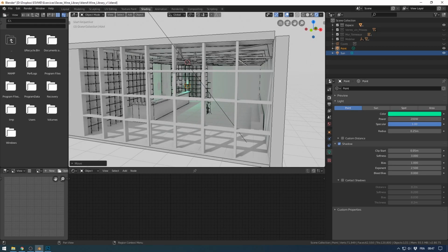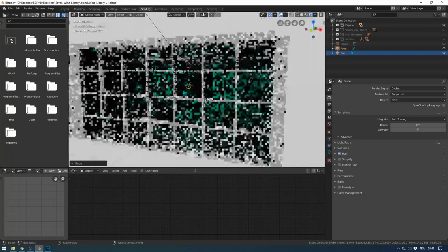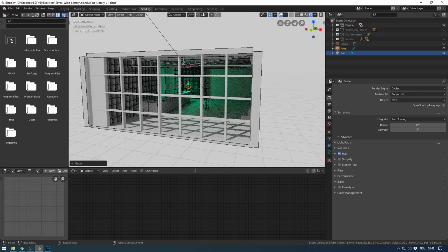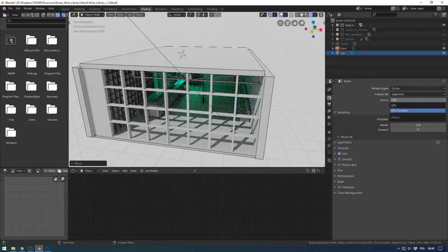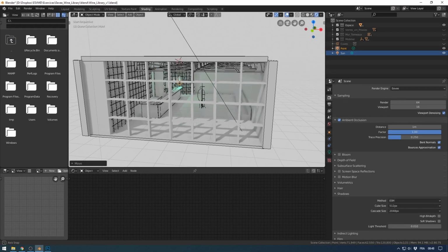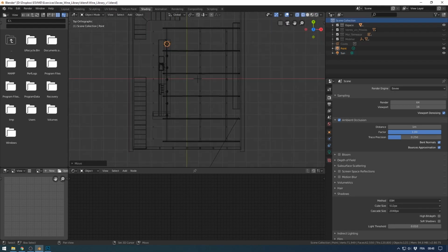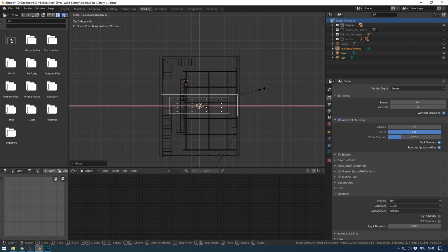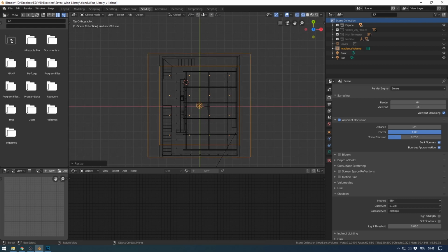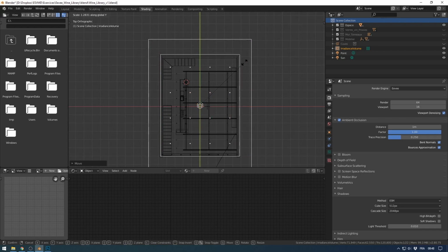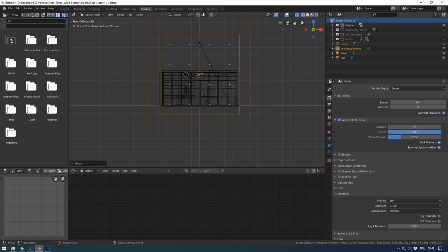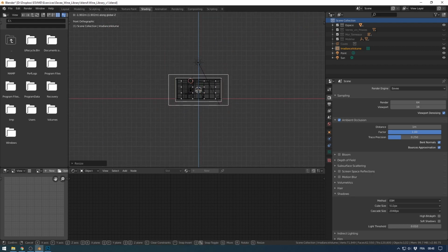And of course, if now I switch to Cycles, it's more realistic, because I have the light bounce inside the room and the back is not lightened. But with Eevee you need to calculate this light bounce, and for that we will use an irradiance volume. You could just scale the irradiance volume according to the size of your scene. You probably already saw a lot of tutorials about that, but I will do it again.